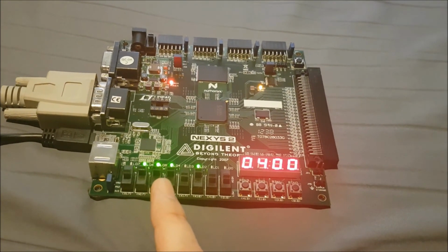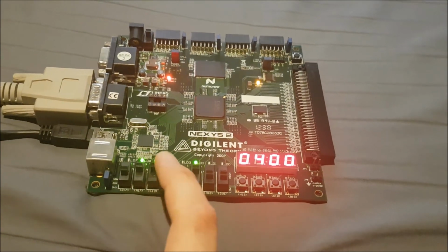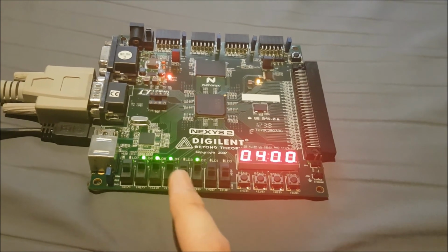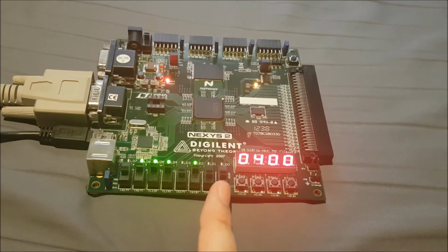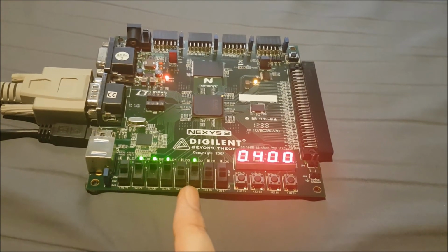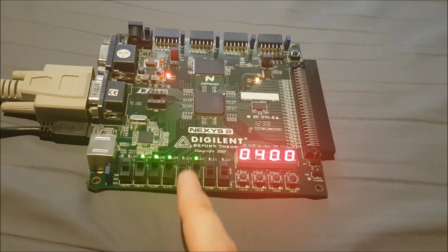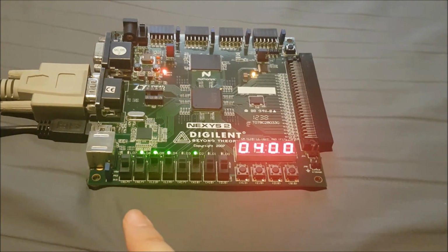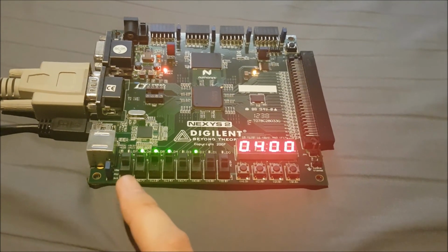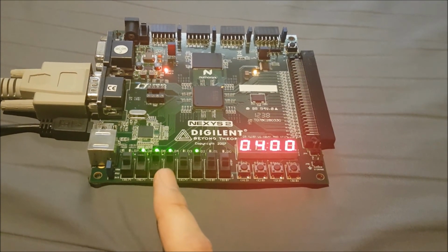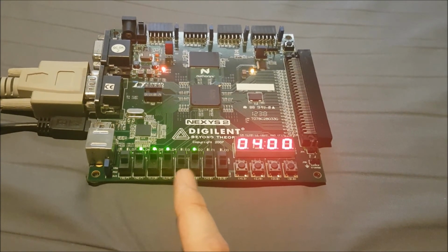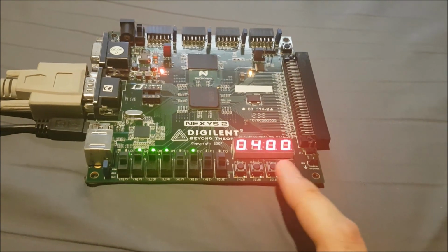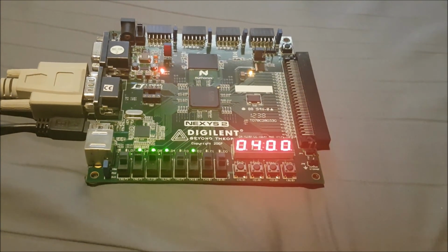This slide switch determines what type of parity is being used. Off means even, on means odd, and these 4 slide switches determine the baud rate that we're going to be communicating at. I want to use baud rate of 9600, so I have to make sure that this slide switch is turned on. To summarize, we're using a communication format of 801, and we're using a baud rate of 9600. All I have to do is reset the system, which I map to this button, and we're good to go.